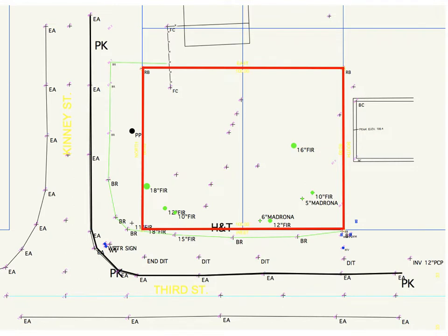The second is the edge of the street, and you didn't do it too carefully since it's about 25 feet from our property. And this just shows, as I mentioned, how a right-of-way is often about 60 or 65 feet wide, and the paved street here is only about 22 feet wide. So there's a large expanse of vegetated area between the edge of the pavement and the property line. That's public space, but generally maintained by and considered usable by the people who own the property.